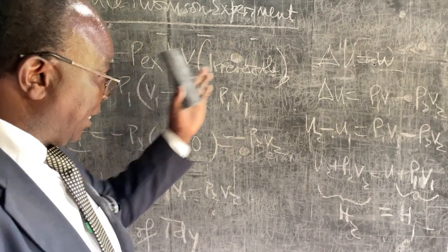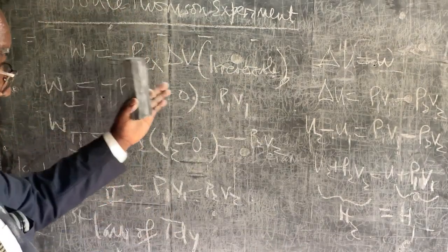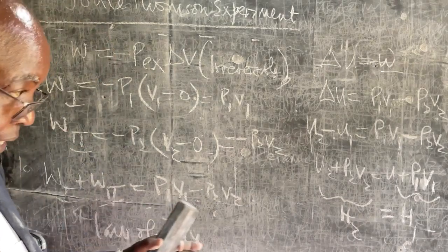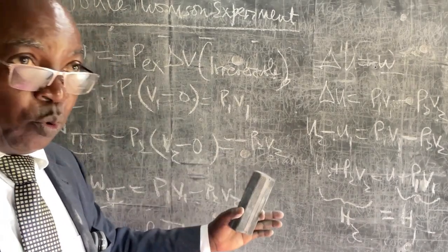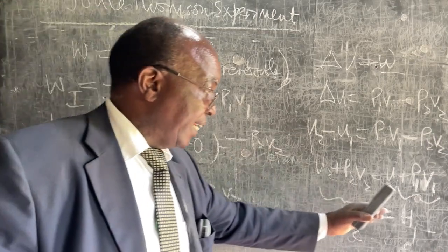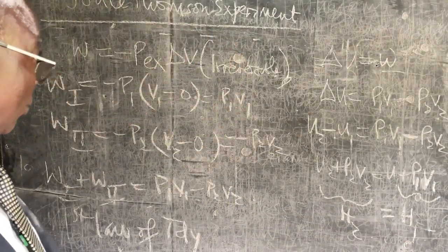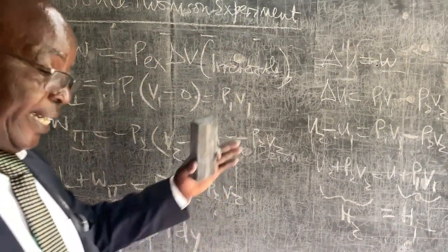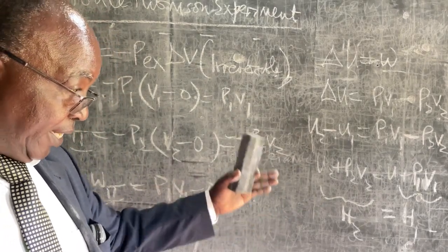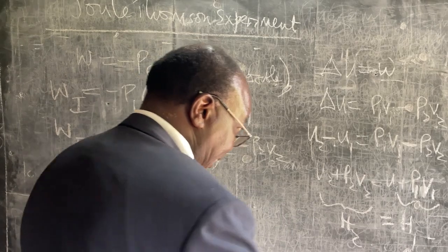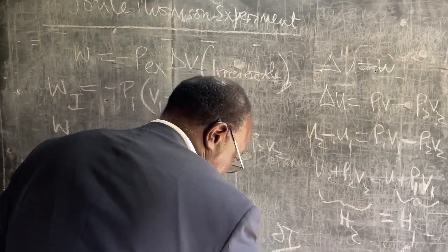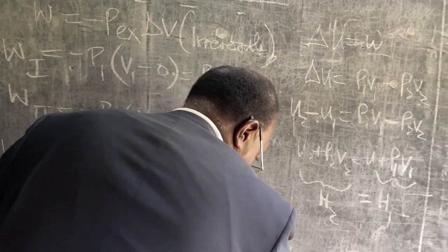So whatever measurements we made of temperature and pressure in compartment 1, and volume in compartment 1, and that in compartment 2, those measurements of temperature and pressure were done under constant enthalpy conditions, which was very fundamental in that coefficient, del T del P at constant enthalpy, which we started off with and were to determine.